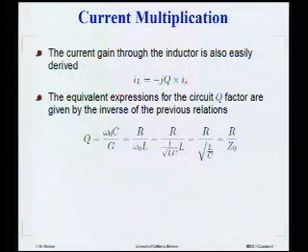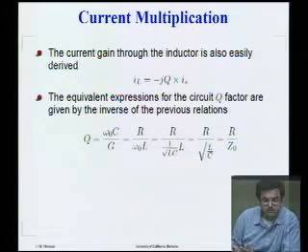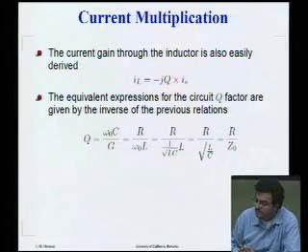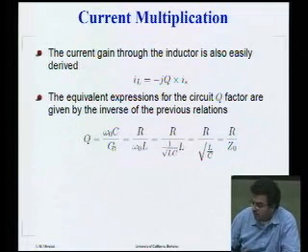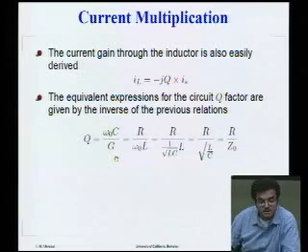And of course, because the current in the inductor is exactly equal to the current in the capacitor with opposite phase, there's also current multiplication going on in the inductor. Now you can see that we can derive several expressions for quality factor, which are all equivalent.